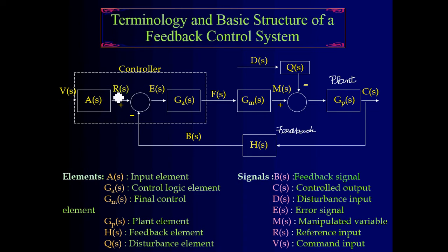This is this reference R(s). The feedback, the measurement of your system, comes in here. Usually this is like RPMs if it is a velocity control system. But this H(s) box transforms the RPMs into a voltage. And this one is also a voltage. So voltage with voltage, then you get a difference. That's what this E is called, the error.